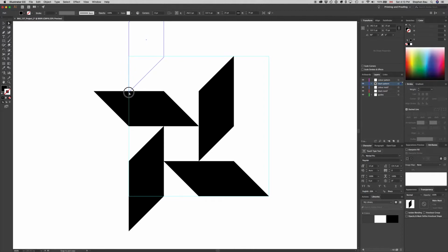until, well, it's not snapping to a point. So I actually want to position this really accurately. I can do that either one of two ways. Either let go here and then using the control bar transform tools, I can change the Y coordinate to exactly 200. And then I know that object is placed exactly where I want it to be.